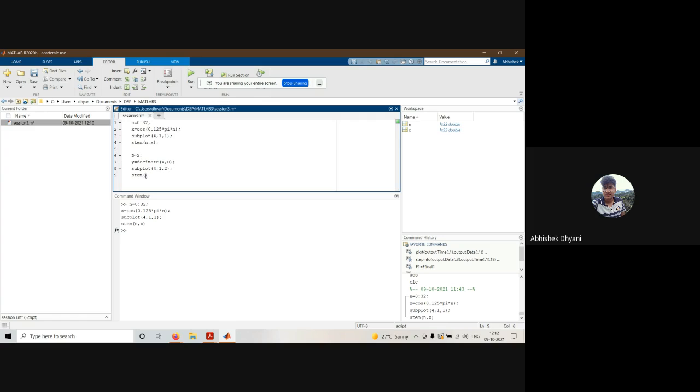Now what happens is that n will change because we have decimated the signal. So if d is 2, let's say x starts from x0. So x0, x2, x4, and so on, the signals will be obtained in y. So we will also have to decrease the number of time indices. So I'll just take the time indices as 0 to 16. I have taken half of them because d is 2, and the number of samples will be halved.